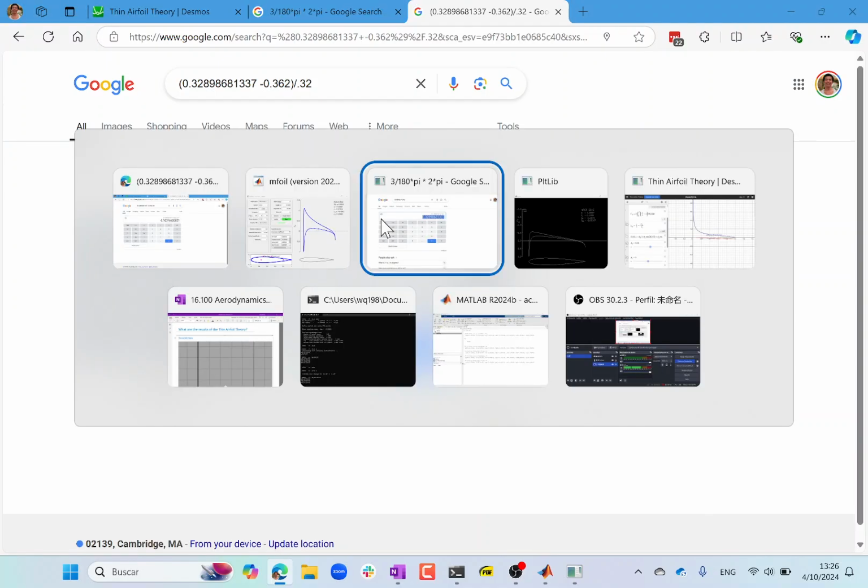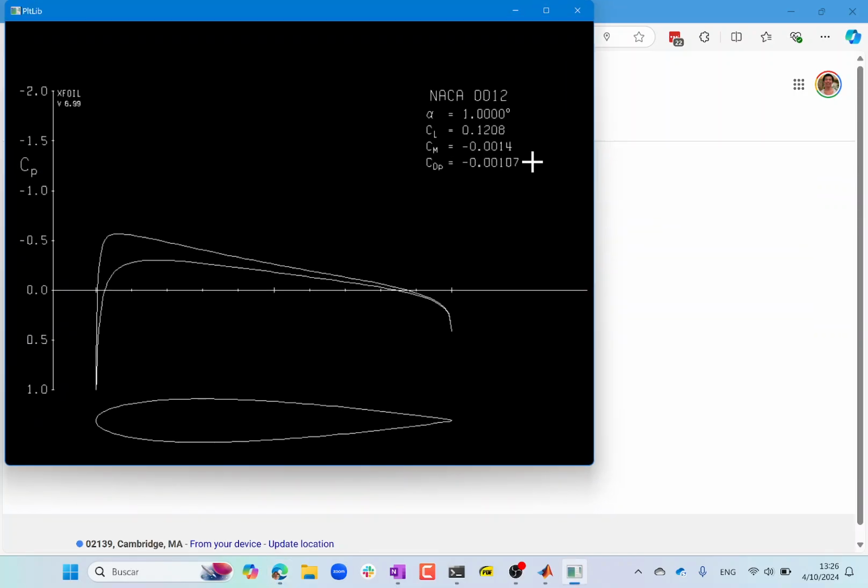Yeah, and our airfoil is actually 12% thick. Okay, 12% thick means the thickness. I mean, the last 2 digits of the NACA airfoil code are the thickness to chord ratio. So with 12% thickness, we get 10% error in lift coefficient. All right, so that gives you an idea of how much discrepancy you expect from the prediction of thin airfoil theory, right?